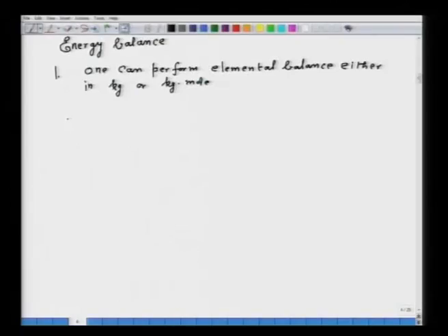Once you have done the material balance of all inputs, it is very important to know where the input of materials is going. Say you have x kg or x kg mole of a certain material in, you have to see how much of that is going into the products. The products could be metal, slag, waste product, or it could be in gaseous form. So, you have to collect all such information, make a box to determine the material balance, and then proceed to solve the heat balance.